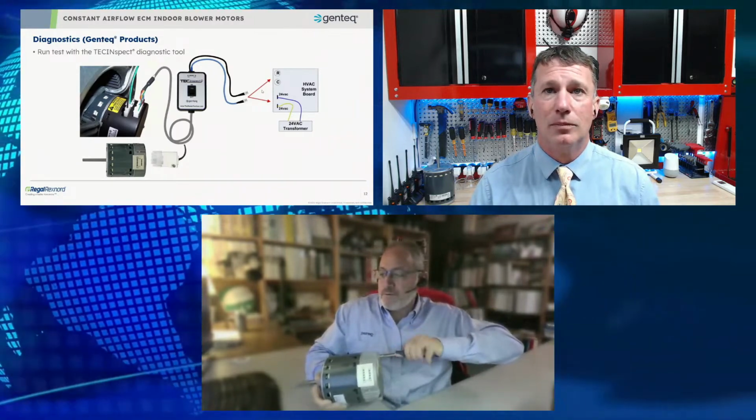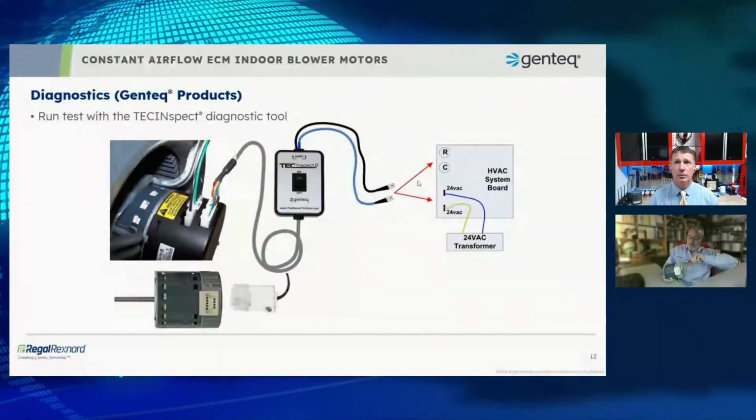One other thing I do want to mention before we go past the screen, and I'm going to take this motor apart so I can hold it up to the camera in a minute. We mentioned that the 16-pin motor, actually both motors, could run at a slow fan speed or at a high cooling speed. So the speed they run is irrelevant; if it's running, the motor's good. But one other piece of information that might be helpful is if you are putting the go-no-go tool on the serial communicating motor, which from our model name is 3.0 for this motor, you may experience where it runs backwards.